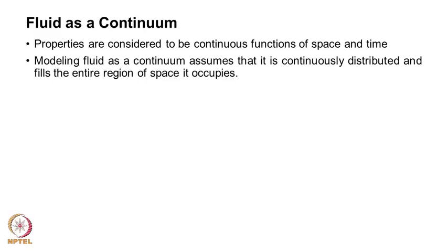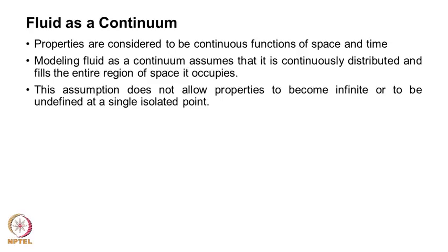So, modeling a fluid as a continuum assumes that properties are continuously distributed and fill the entire region of the space it occupies. Now, this assumption does not allow properties to become infinite or to be undefined at a single isolated point.